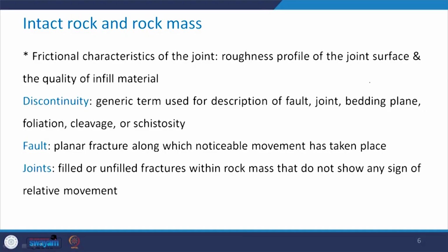Frictional characteristic of the joint, what is it? Because we have already discussed the intact rock, but this aspect, the frictional characteristic of the joint, we have not discussed yet in detail. So basically this is the roughness profile of the joint surface and the quality of the infill material. From where is this infill material coming?